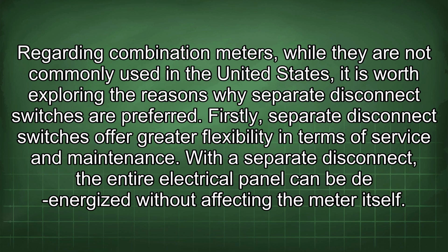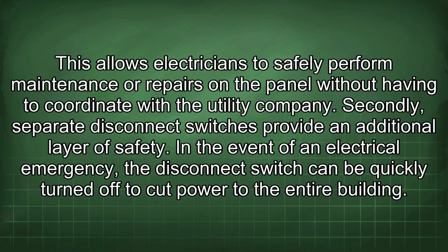Regarding combination meters, while they are not commonly used in the United States, it is worth exploring the reasons why separate disconnect switches are preferred. Firstly, separate disconnect switches offer greater flexibility in terms of service and maintenance. With a separate disconnect, the entire electrical panel can be de-energized without affecting the meter itself. This allows electricians to safely perform maintenance or repairs on the panel without having to coordinate with the utility company.